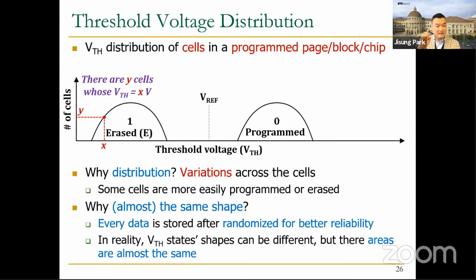Suppose only one cell in a NAND string is programmed while the other cells in the NAND string remain erased. Then the only programmed cell, whose threshold voltage is increased rapidly, leaks the charge inside its floating gate due to the huge voltage gap between adjacent cells. And it in turn likely causes a retention error more easily.